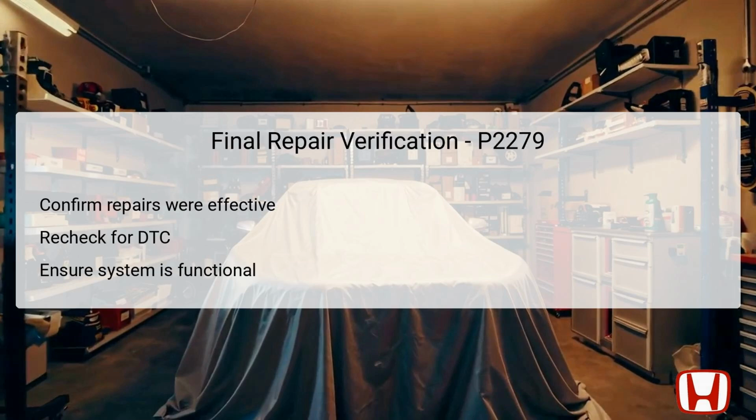Final repair verification is a critical step following the troubleshooting process to ensure that effective measures were taken to address DTC P2279. After any repairs or replacements have been performed, it is essential to conduct a follow-up inspection to confirm that the issues have been resolved. Recheck for the presence of DTCs using the Honda Diagnostic System, HDS, to ascertain if any new codes have emerged or if P2279 still persists.